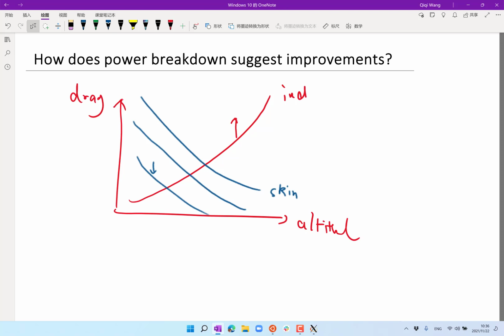So this is probably the first thing we are going to do in the design. And the second thing is to do a balance and stability analysis to figure out, now that I have the shape of the wing, I know the chord, I know the span, where should I put it relative to the fuselage? How big of a tail do I need? And how long does the fuselage have to be so that the tail has enough moment to balance it? These are the two primary things we are going to be doing this week.